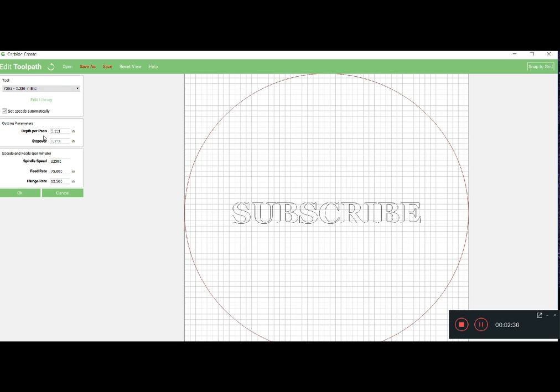Now, I've seen a lot of videos where people say, don't mess with the cutting parameters. Well, guess what? You definitely want to mess with the cutting parameters. If not, your machine is either going to go way too slow for you, it's going to take forever, or you're going to take too much off, because you can see there's already preset feed rates and everything in here, which I'm fine with this right here, but on some of the bits, they're just not set up very well.